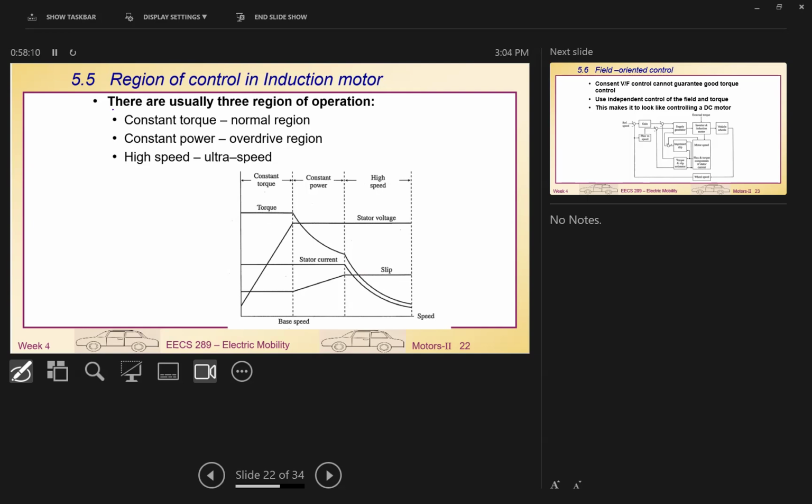But basically, when you further weaken the field in here, your field cannot become too low. For instance, if it goes far too low, then the flux cannot link to the other coil. So in this case, we have a limitation. We cannot weaken the field too small because of the physical geometry. So when you find that your flux cannot be reduced further, you need to reduce your current. Then that will push you into this region of high speed.